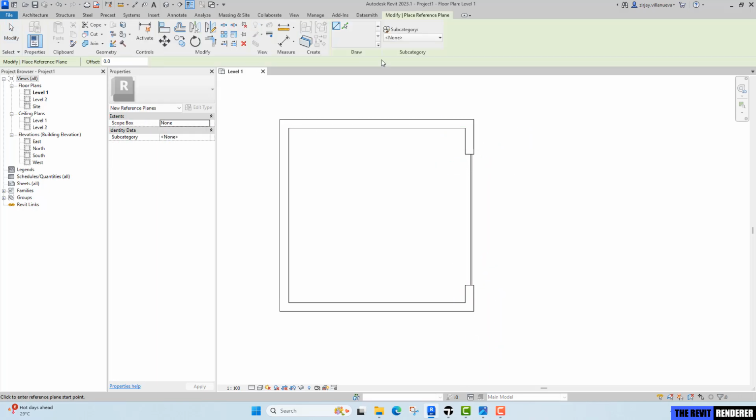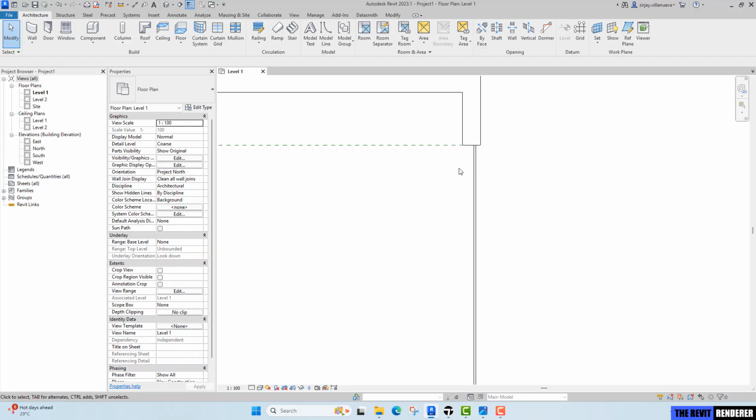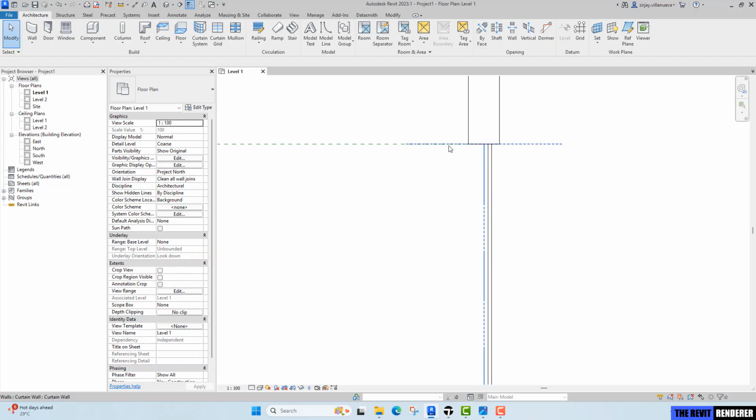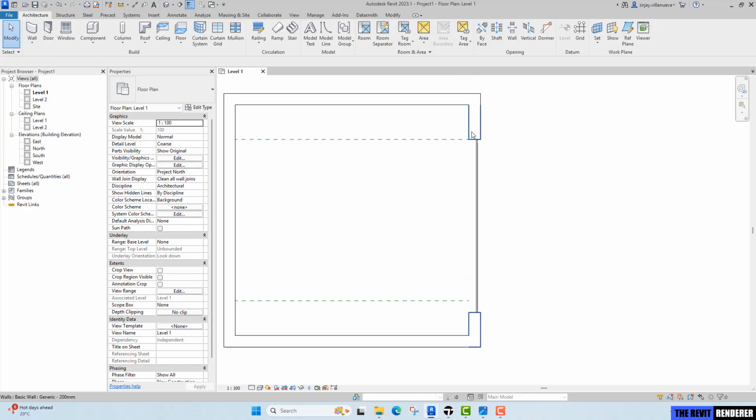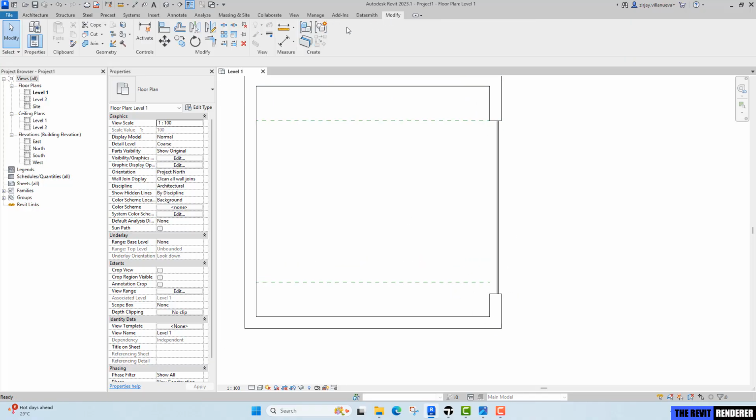And just before I continue, I'm just gonna set out 600 mm from the top and bottom wall, because I only want my window to go all the way up to here. So this one is just nice, perfectly 600 mm away from the wall. This one I'm going to use the modify tool, extend up to this line only.